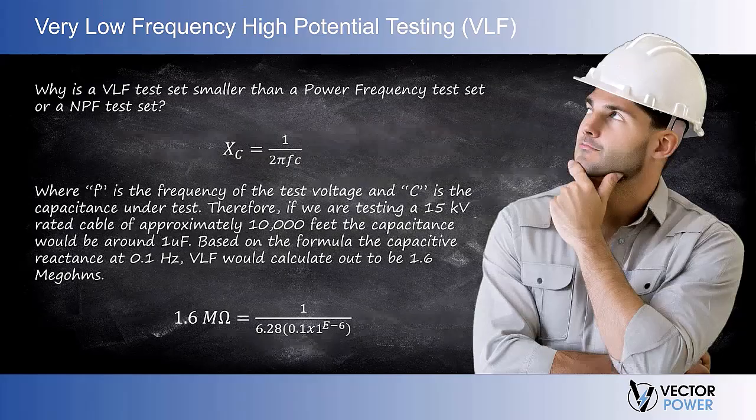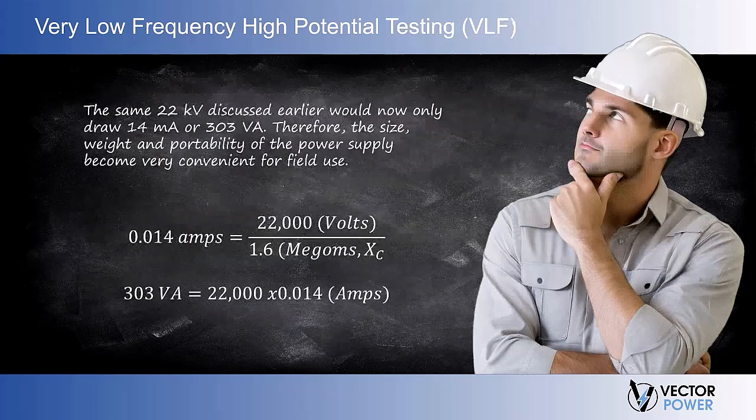So, why is a VLF test set smaller than a power frequency test set? Well, if the test frequency were dropped to 0.1 Hertz, the capacitive reactance, as calculated earlier, becomes 1.6 megohms.